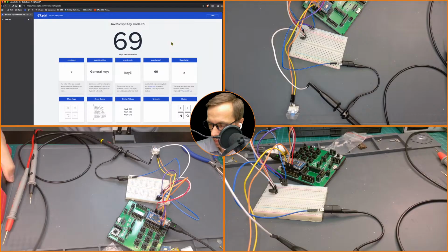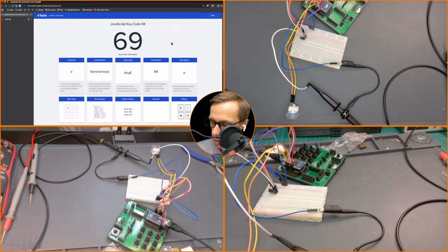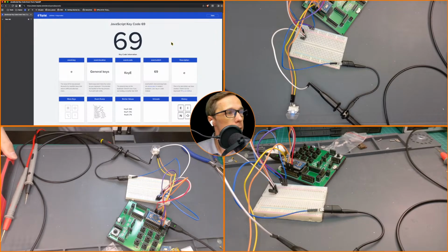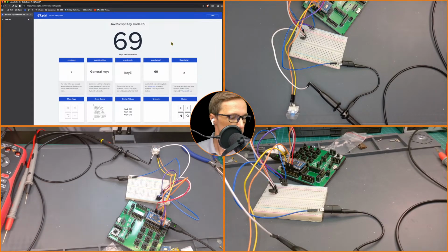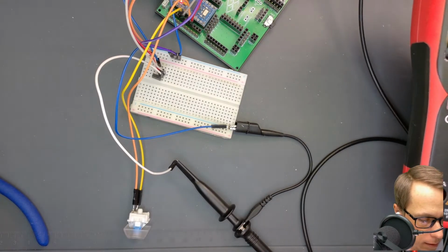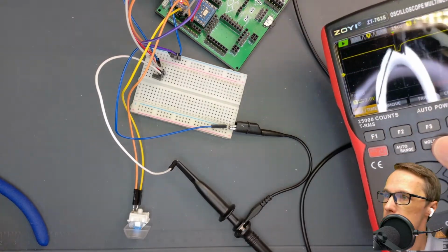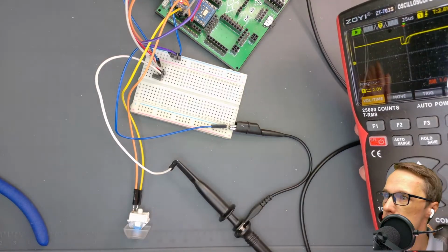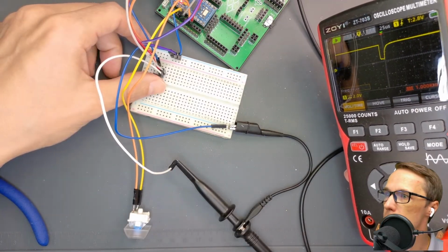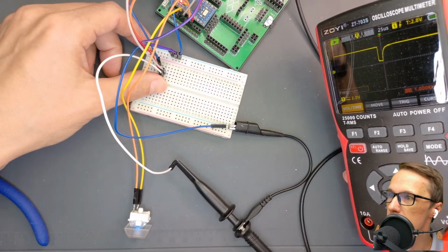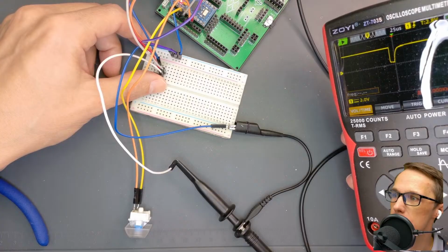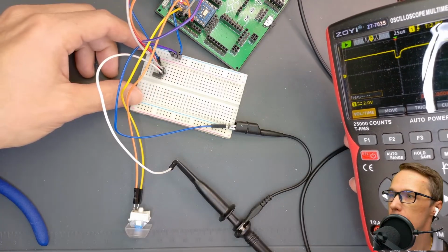And maybe we can take a look at the same time if we can get anything out of the oscilloscope. I think I need a camera for the oscilloscope. So this is how it looks, and you can see if I put my finger, this square goes all the way to 0. This is where it's interpreting the key, which is great.